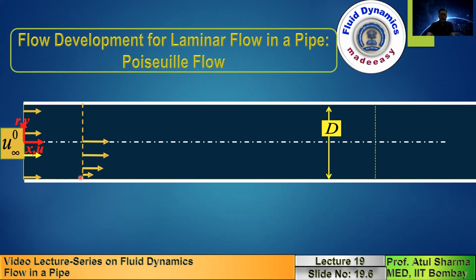And there is a stickiness between the different layers of the fluid. The fluid which comes into contact with the walls of the pipe, its velocity is 0. But since the fluid is entering with a larger velocity, due to the stickiness of the fluid, the layer above has a decrease in the velocity, and slowly a velocity gradient sets in.